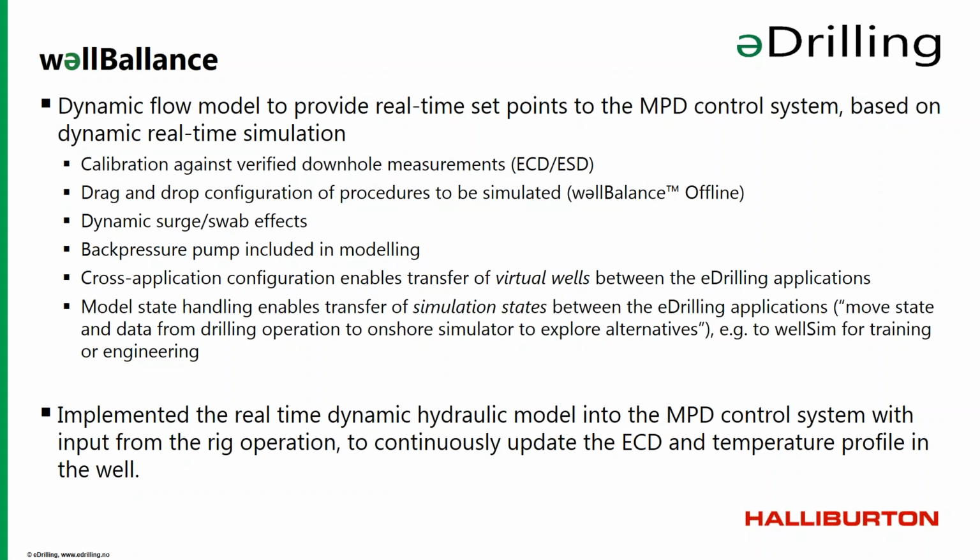In short, we have implemented the real-time dynamic hydraulic model into the MPD control system, where we take input from the rig operation to continuously update ECD and the temperature profile in the well. And as Ingvild mentioned earlier, you decide if you want to keep a certain pressure at the bottom hole, at the casing shoe, or anywhere else in the well. The model back-calculates all the time what pressure you need to keep your choke at.